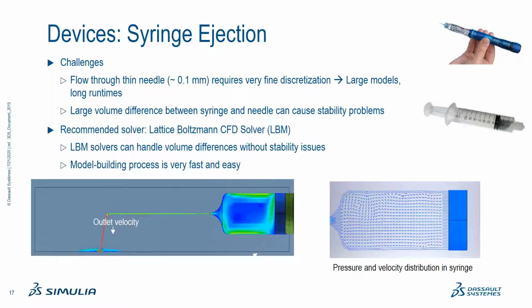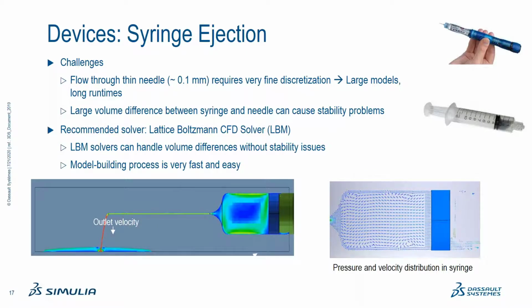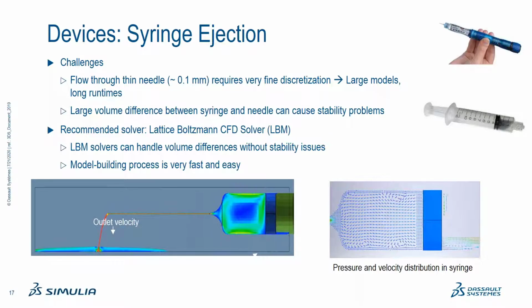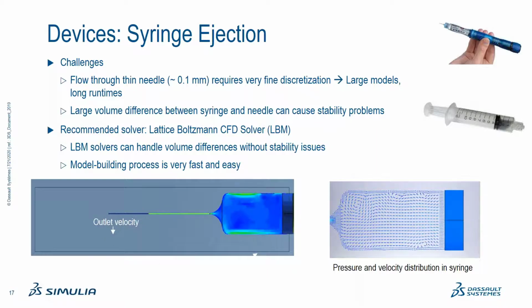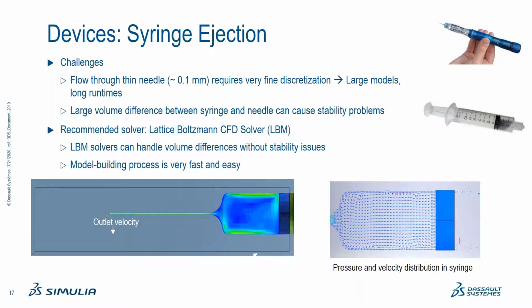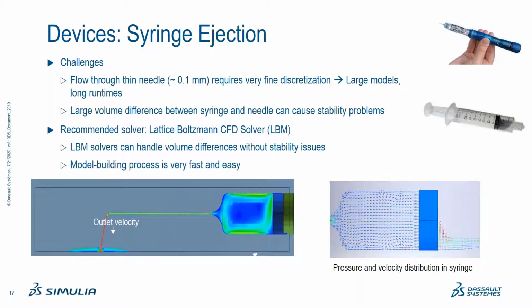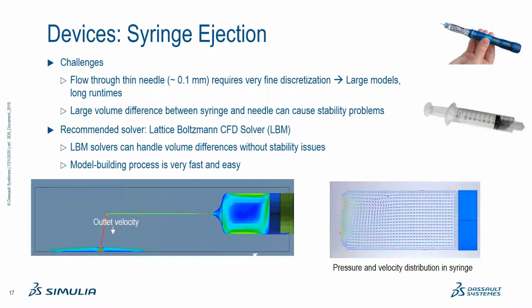There's very little flow taking place in this limiting condition, and the fluid is being nipped down from a large volume to a very narrow diameter. Again, a simulation very hard or impossible to accomplish with meshed fluid domains. The potential for leakage around the plunger is explicitly captured because the fluid can flow between the flexible plunger and the flexible syringe wall. This is especially valuable capability when exploring the effects of plunger misalignment or engineering wearable devices to deliver a drug via a micro pump.